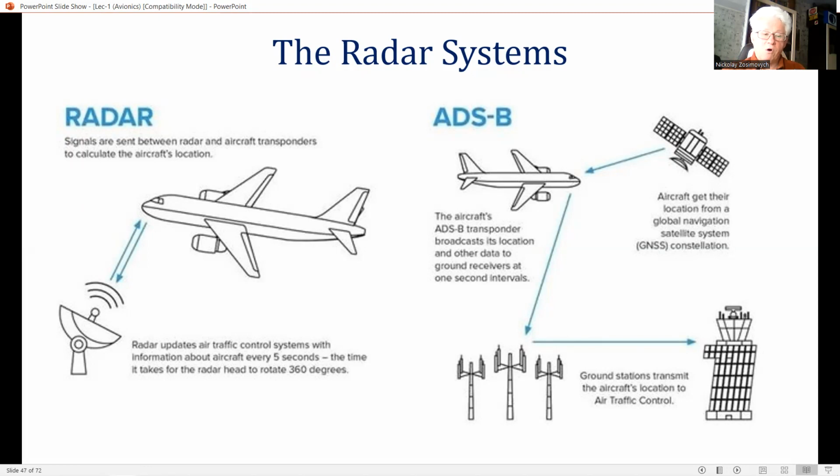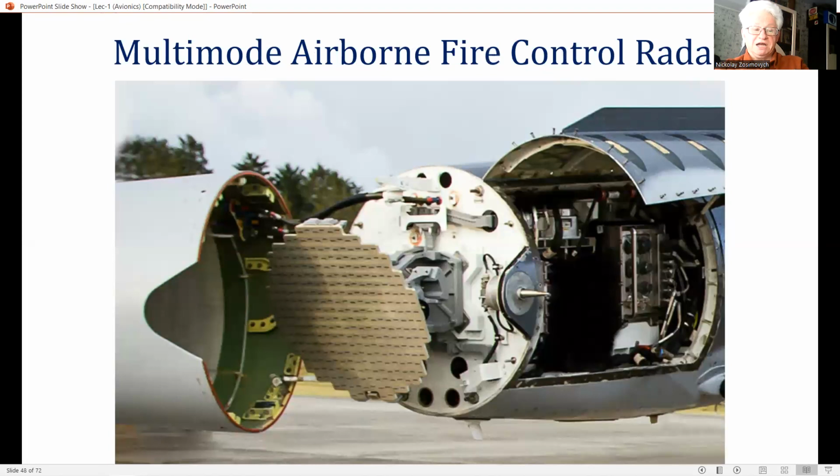In the ground attack or mapping mode, the radar system is able to generate a map-type display from the radar returns from the ground, enabling specific terrain features to be identified for position fixing and target acquisition. Modern fighter aircraft generally have a ground attack role as well as the prime interception role and carry very sophisticated multi-mode radars to enable them to fulfill these dual roles.